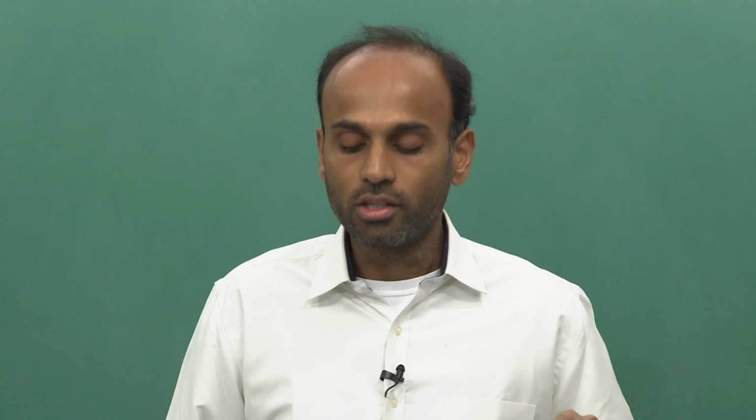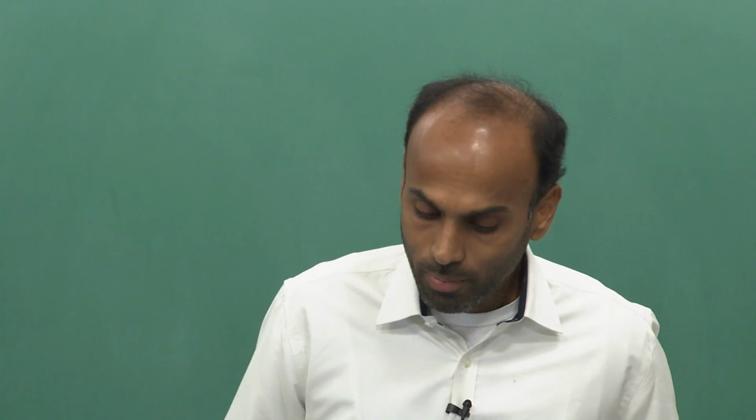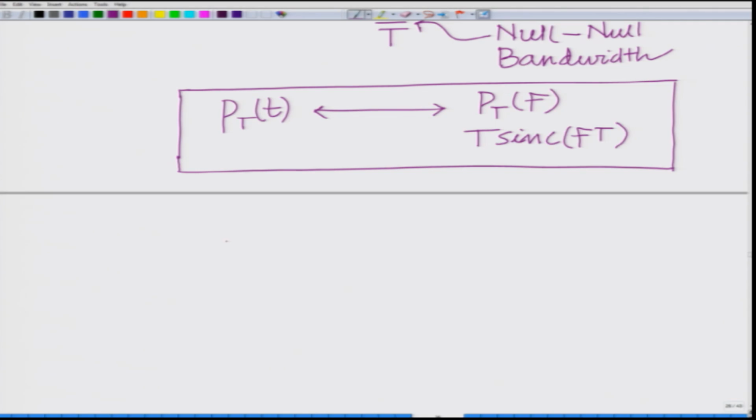So, in this module we have defined the Fourier transform of a continuous time aperiodic signal, the inverse Fourier transform, that is, given the Fourier transform, how to derive the time domain signal, and also illustrated the computation of the Fourier transform through an example. And just to conclude, remember,